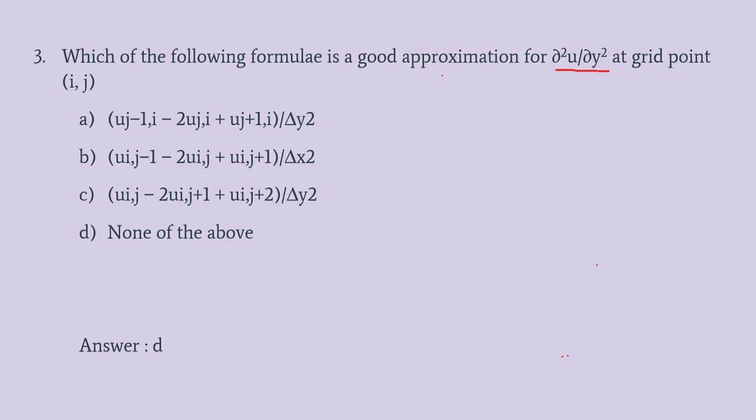Suppose for a duct, you can think of a pipe flow, fully developed pipe flow. We will be giving only one dimensional u velocity. But inside that pipe is actually a three-dimensional space. Inside that space, we are discretizing. If we are discretizing the circular region inside a cross section in a pipe, the u can vary with respect to y and z.